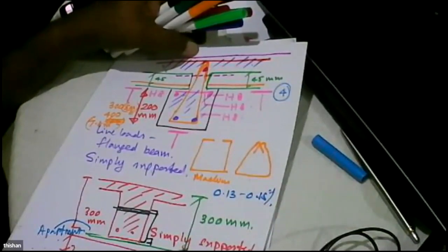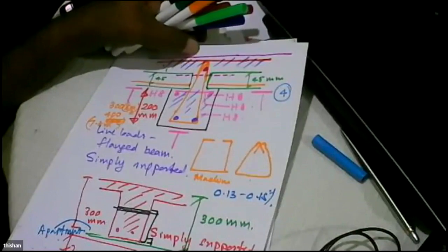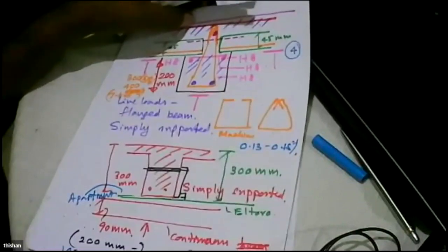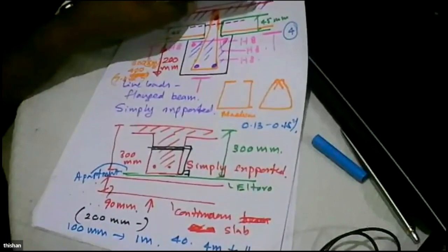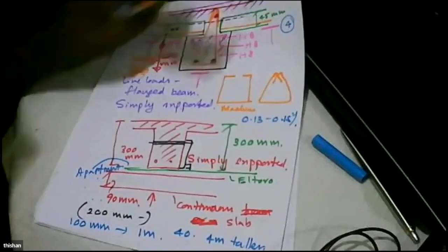Now we are casting only a small piece of slab. So can you have any shrinkage cracks in such a scenario? Absolutely not. So we allow the shrinkage to take place before we cast the slab. So we don't have to satisfy this minimum reinforcement requirement. Do you agree with me? Yes, sir. Bandhuka? Yes, sir.